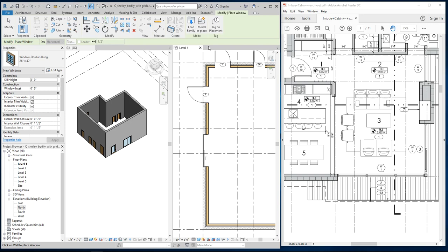And if I'm over here in my floor plan level 1, this window is automatically associated with level 1, okay, just like the doors. The only difference between the two is that a sill height is built into windows, right, and it's kind of defined. So I get an out-of-the-box 3-foot sill height for this window because, well, I'm not even going to say normally, but not even most of the time. I would, maybe a stereotype. We'll stereotype windows tonight. Very stereotypically, windows have a sill height, like all of these windows. They don't usually go to the floor, right? So a sill height is built in.